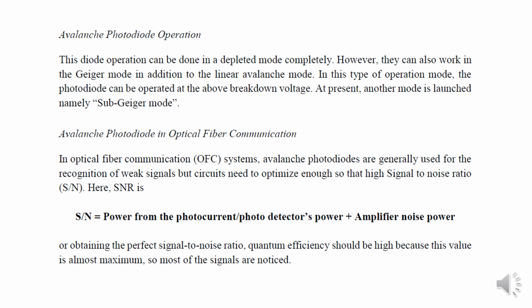As for the characteristics, avalanche photodiodes are highly sensitive and high speed diodes, which use the internal gain method that works by applying a reverse voltage, as compared to the pin type photodiode. This diode measures low range light, so it is used in different applications where high sensitivity is required, like measurement of optical distance and optical communication for long distance. That's all. Thank you.